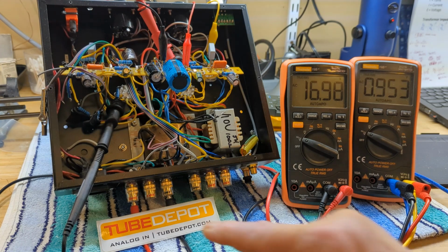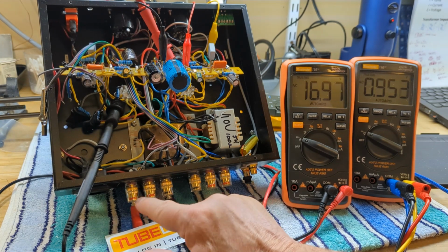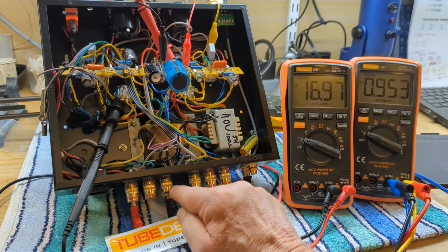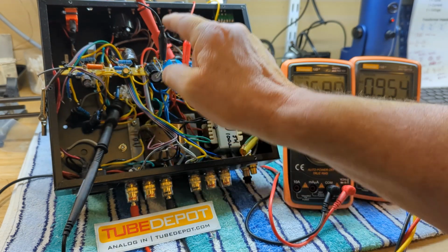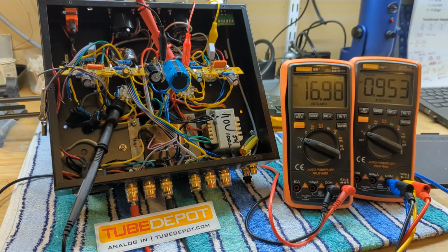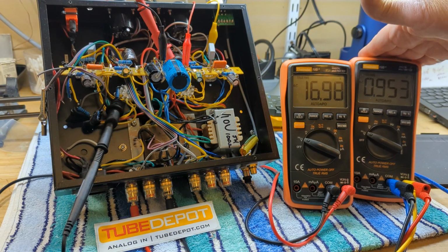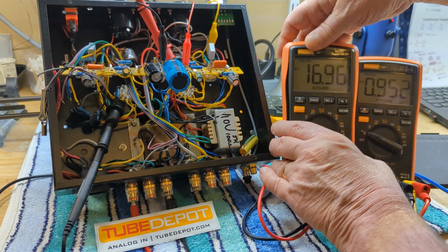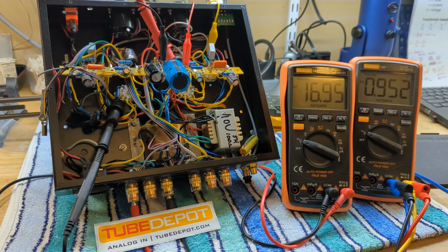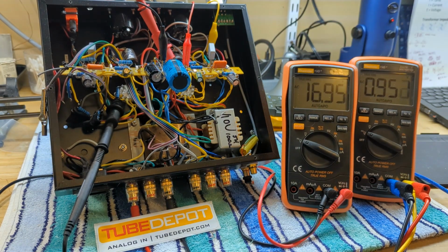Now, we have an 8 ohm output. These are the output connections here: the ground, 4 and 8. Ground, 4 ohm, 8 ohm. And these connections are going inside the amplifier to the primary of the output transformer. So when I put my voltage into the speaker terminals, I will measure the reflected voltage coming out on the output transformer. A little bit of glare on that, but I guess that's okay.